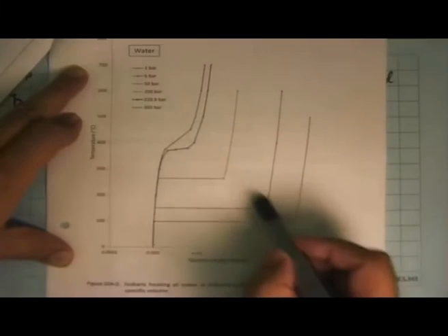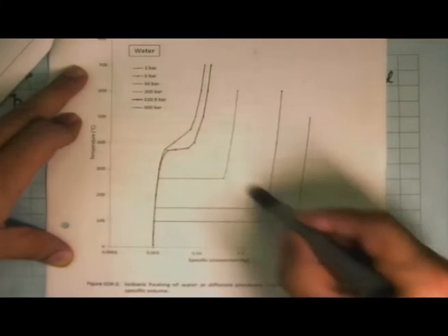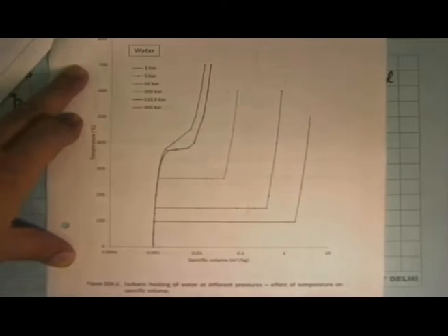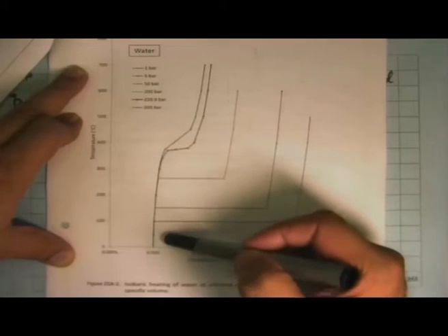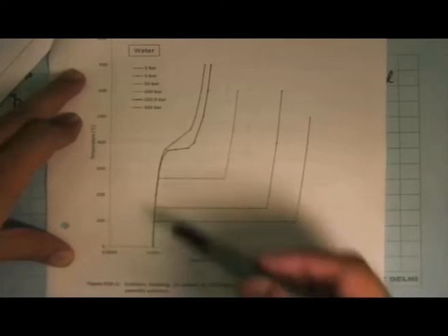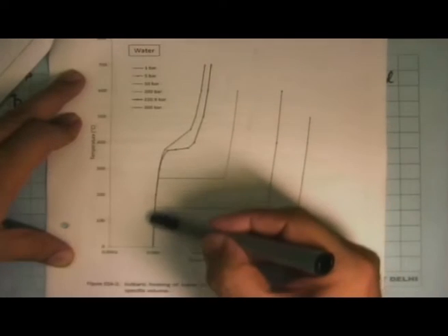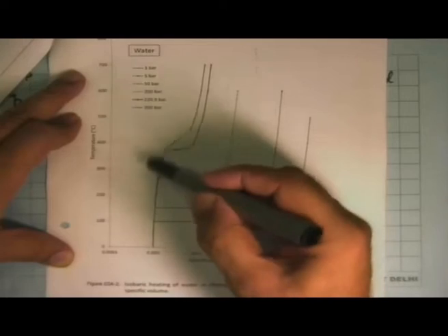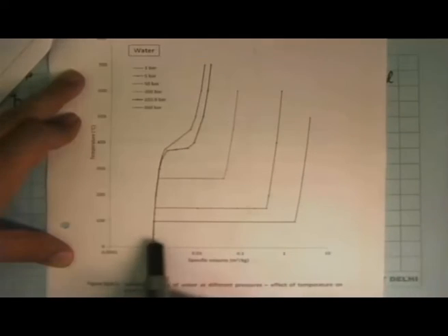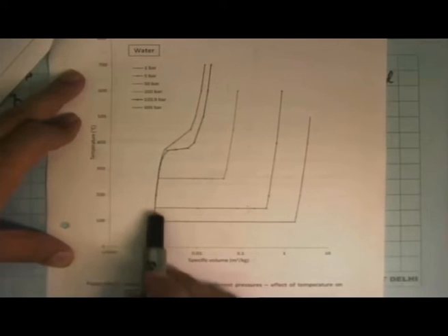And so these are all the saturated vapor states, these are all the saturated liquid states. And what you see here is what I was just mentioning, that the way I made the drawing qualitatively, my freehand, is quite unrealistic in what the actual numbers are. You can see here all these points are practically on one another, that the effect of pressure all the way to 300 bar versus 1 bar, there is hardly any difference in the properties at low temperatures here.